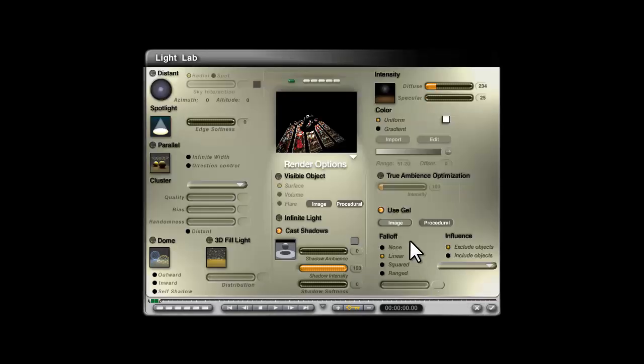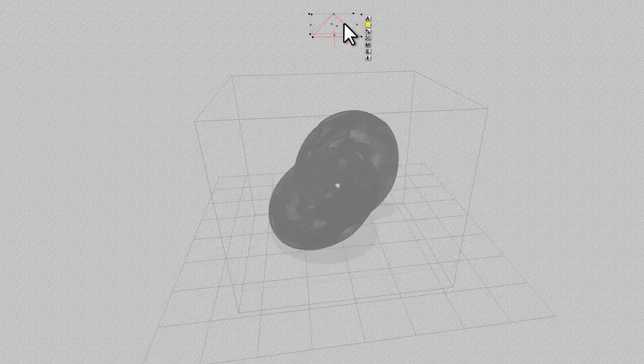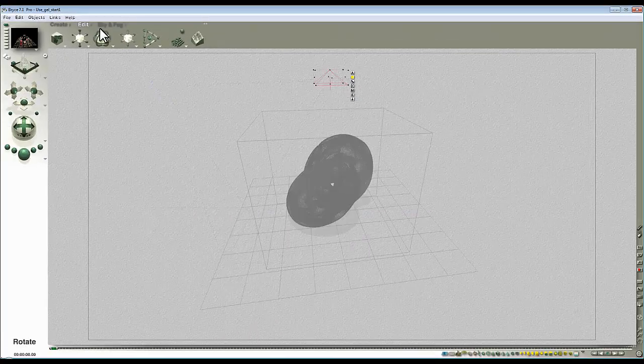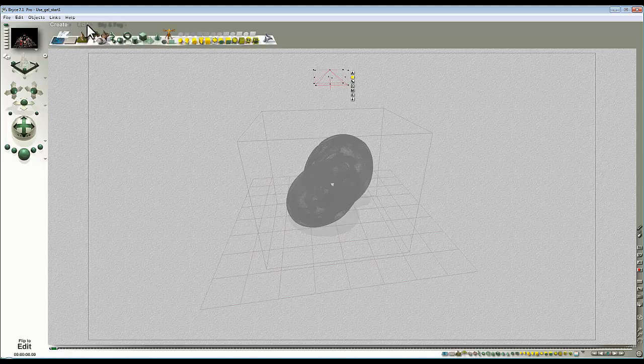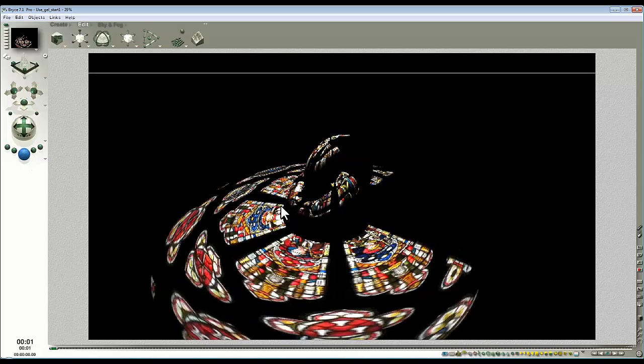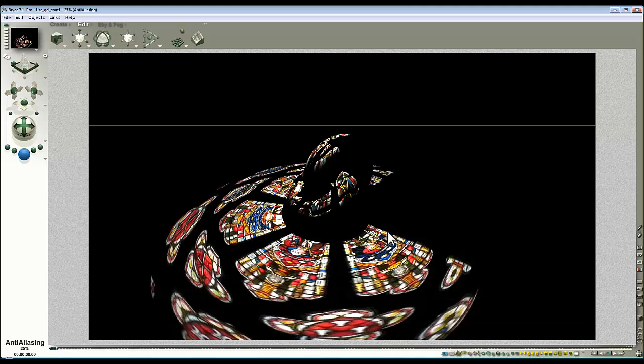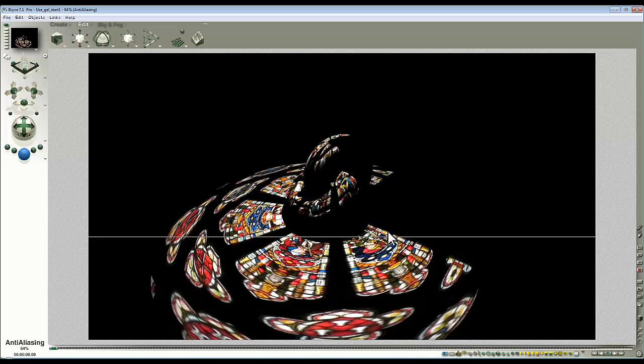To help explain that, I can swap this, which is essentially a pyramid, for the cone. If I go to the edit shelf, that's the one option I want here. This allows me to convert selection to. If I swap it to the cone, which represents our round spotlight, then when this gets projected out, suddenly it's not like a flat sheet in front of the light source projecting out.